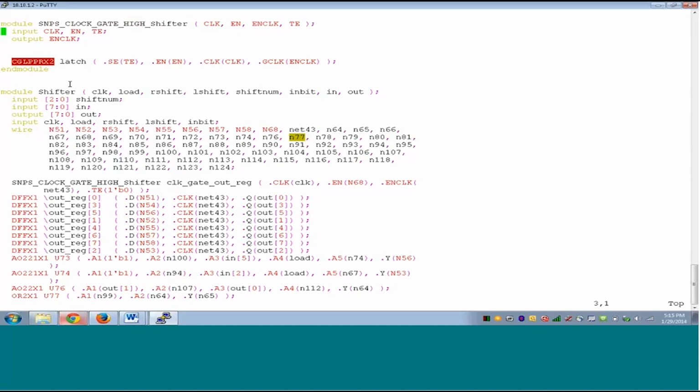I'm not going to do the set clock gating style command in this session, but you can try it if you want. But the result should be similar, because the only thing you will probably play with is the register bank width. The default is 3, which I think is good enough. People increase it, in fact, they don't decrease it. So you can increase it to either 4 or 8 based on what suits your design, what suits your area and power number.